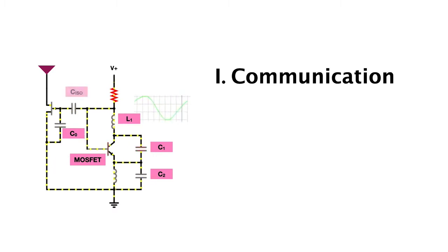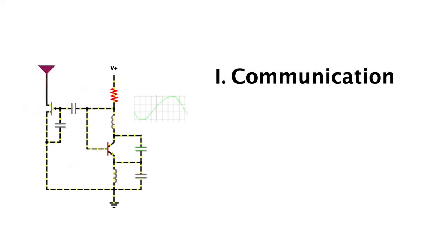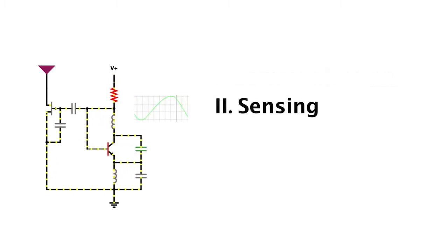An isolating capacitor removes any DC bias from the output signal and feeds into a JFET that translates voltage changes from our signal to impedance changes in the antenna. Many types of analog sensors could be easily integrated into the Mars system by modulating the oscillator frequency.